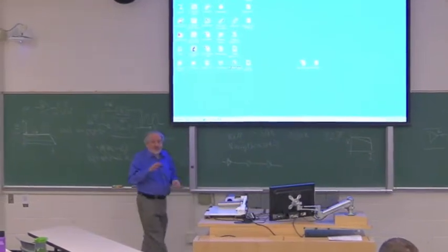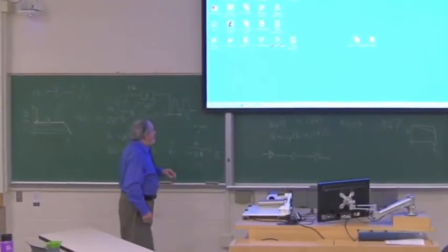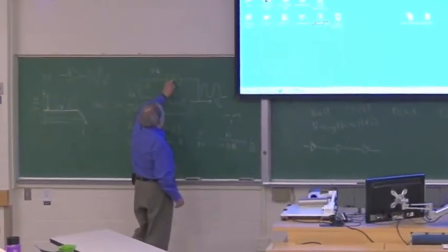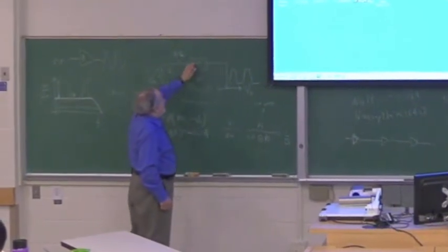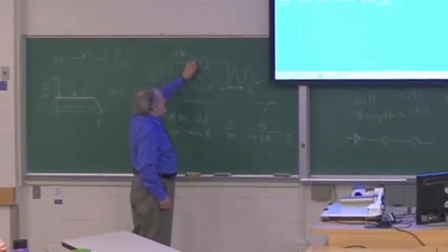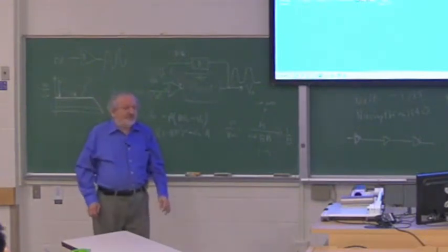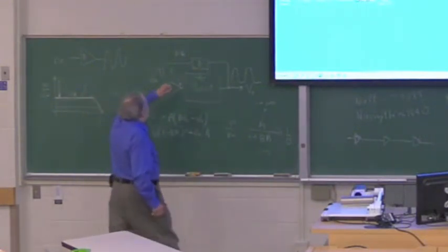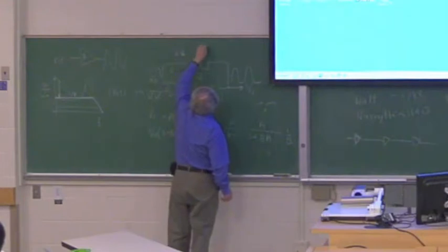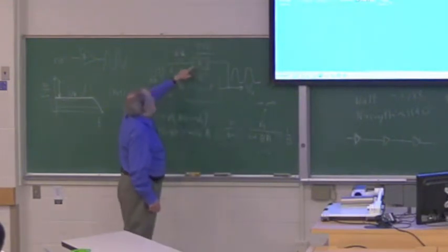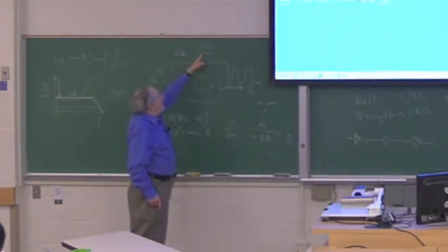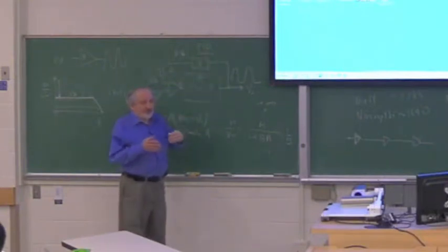You heard the term PID control, right? Yeah. So usually here in the feedback, you have proportional elements, and you can put derivatives or integrators, as you learned in the control courses. So in general, it's called PID control because you can use proportional, integral, or derivative to match the job.